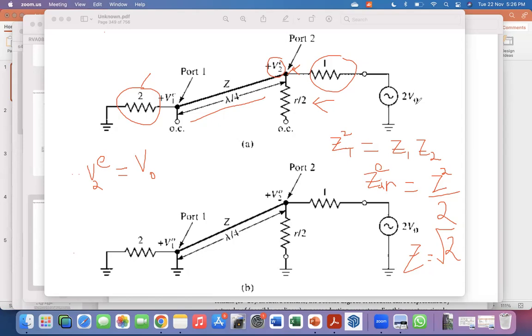We are now going to find the same voltage, but now here on this side, which is V1E, because we need to compute the voltage at this point to know the full S matrix. This we do using the transmission line equations. Okay. So we define the point port 1, this point here, as x equal to 0.